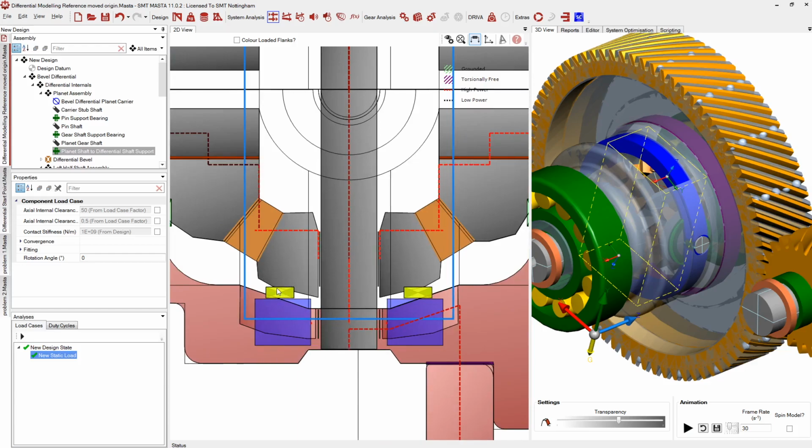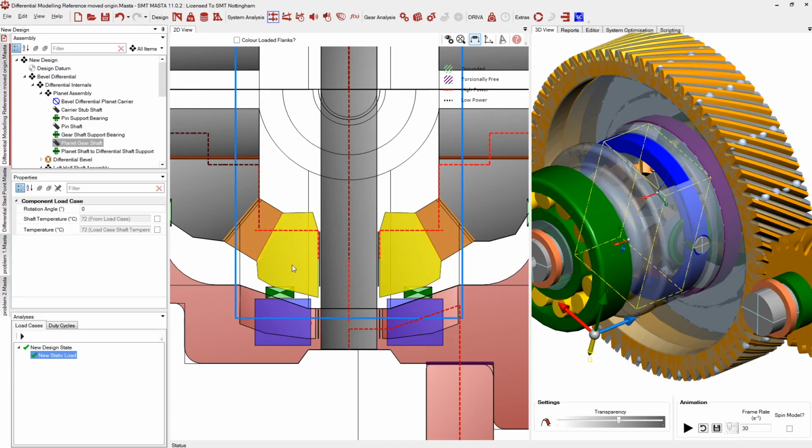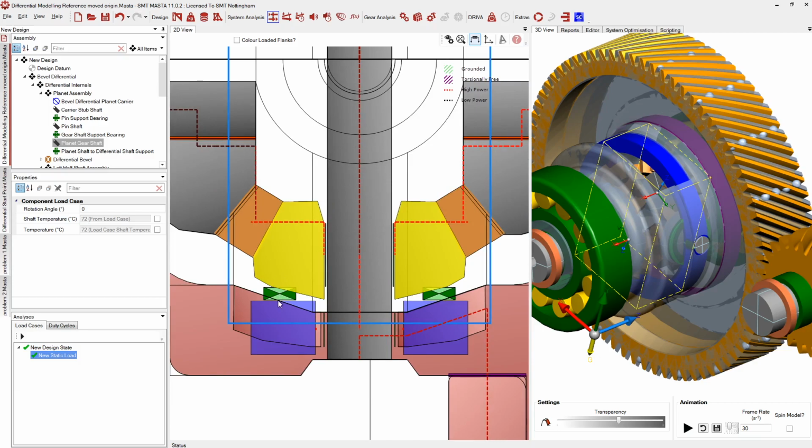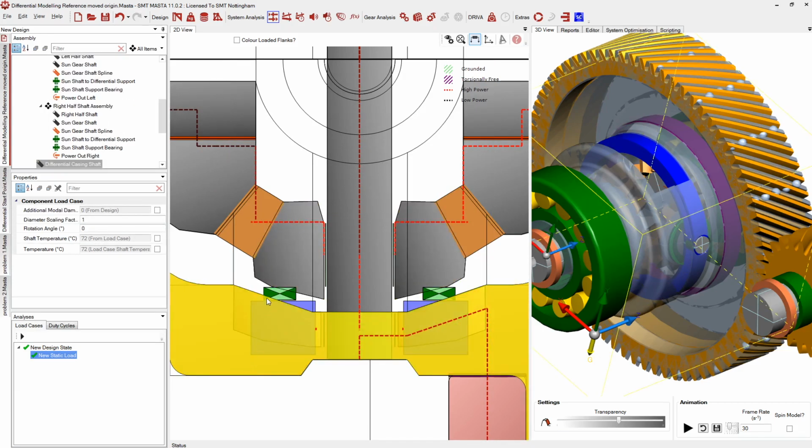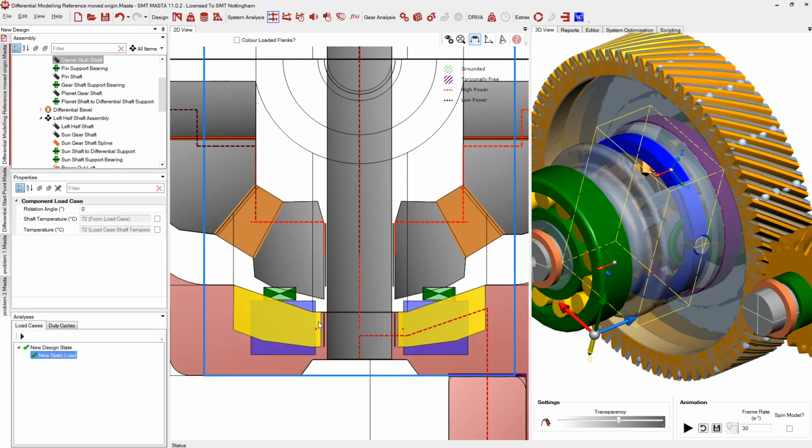So if I had the axial clearance bearing connected to just the differential planet hub here, that's fine. But then it wouldn't be able to connect directly to the differential housing on the other side because it's in that opposite orientation. So the reason for this stub shaft here is so that we can still have something to connect the other side of that clearance bearing connection to.